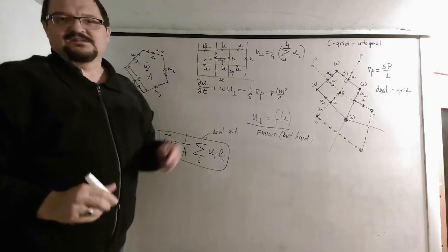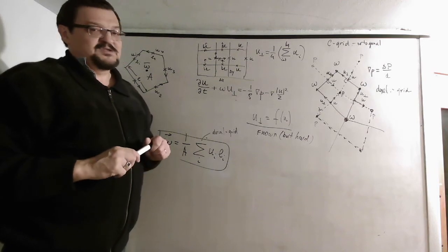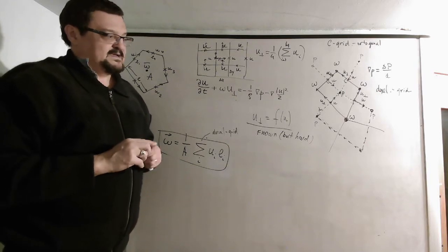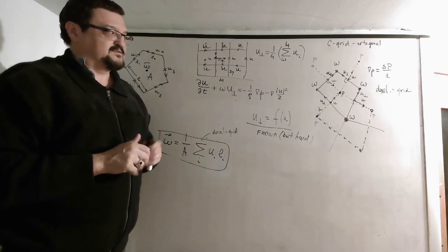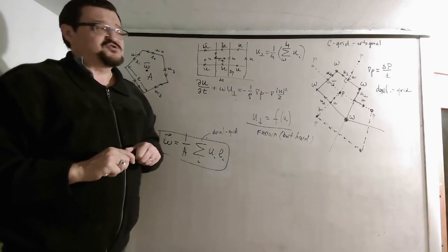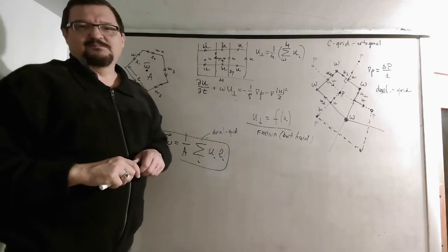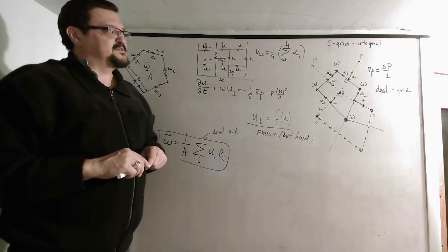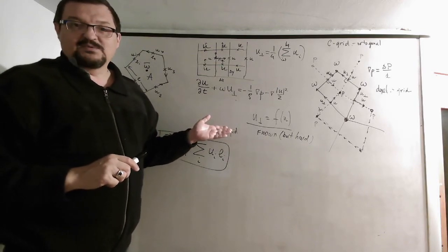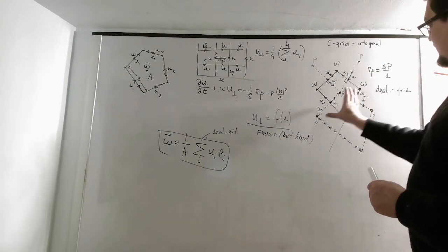And so that's basically the essence of this. And many models based on finite volume actually use this method rather than the method that we talked about previous time. I actually like the one we talked about previous time more, but this method is kind of beautiful and allows you to use finite volume on any grid. There is no x here or y. What we are operating on in this method is just basically distances between certain points.